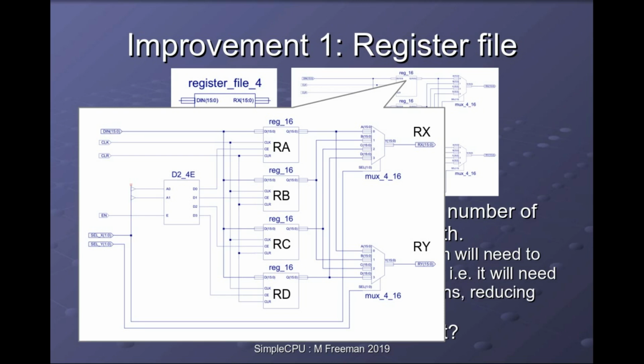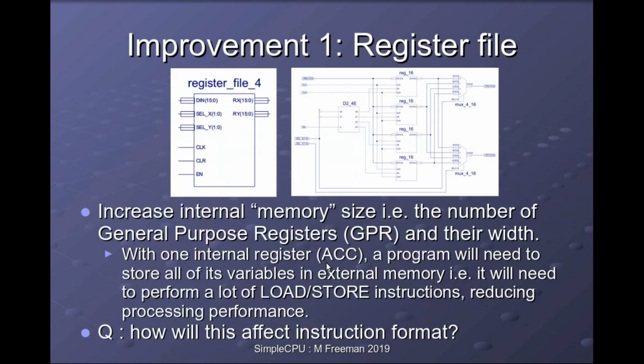And that was an advantage for the accumulator-based architecture. You didn't need to define within the instruction where one of the operands was coming from and where the result was going, because it was always the accumulator. Now we have 4 general purpose registers, so now we need some way of identifying the source and destinations of our instructions. You will also notice there's an additional 4-way multiplexer down the bottom here, and we use that for additional addressing modes that we'll be looking at later.